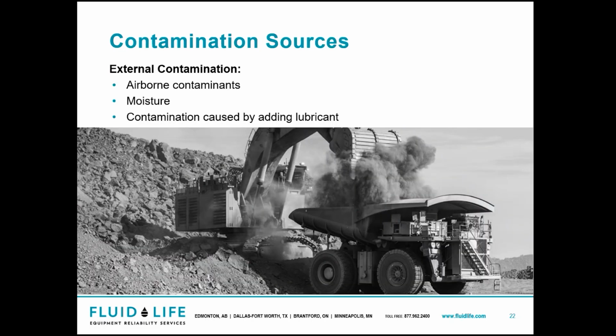So external contamination, airborne contamination, moisture contamination caused by adding lubricants. So like I mentioned, open up a breather, dirt is going to get in there, get circulated. You're going to need to breathe air into that reservoir, so you need to have caps and breathers. And for the odd time you see that open piece of equipment where people think, oh, you don't need the cap on here, it's not that dirty. Even during an oil change, you're opening up that component to the atmosphere, right?